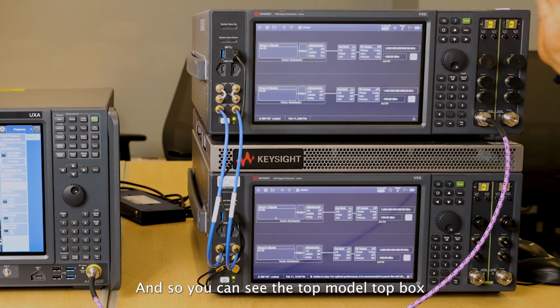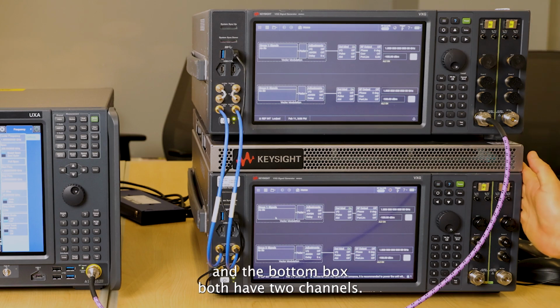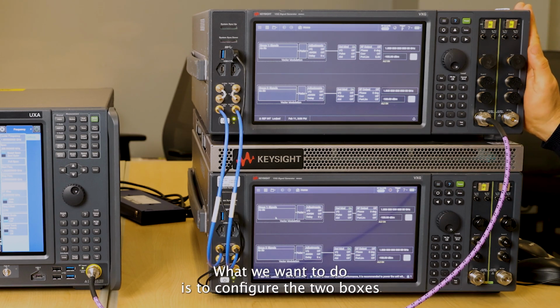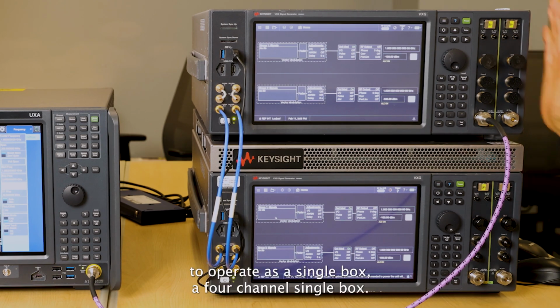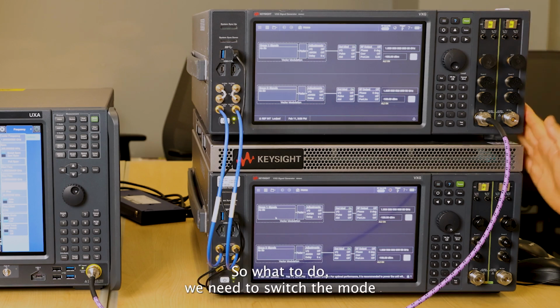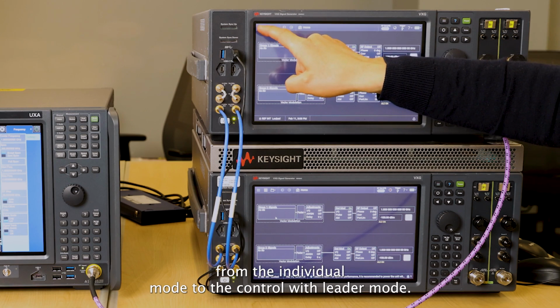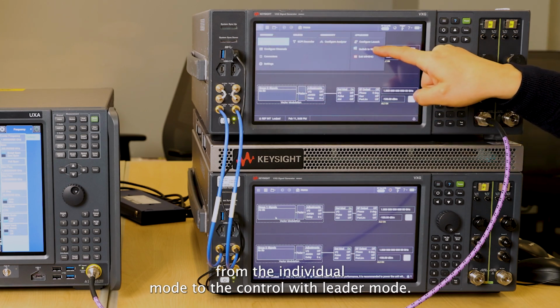You can see the top box and the bottom box both have two channels. What we want to do is configure the two boxes to operate as a single box, a 4-channel single box. So what to do? We need to switch the mode from individual control mode to the control with leader mode.